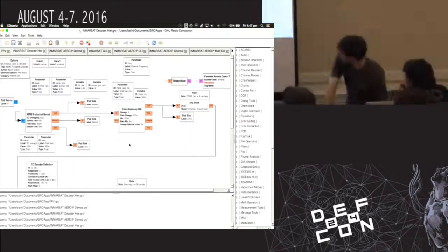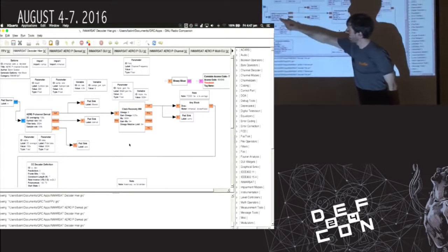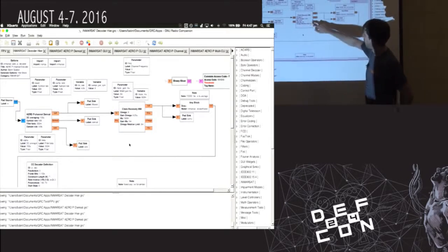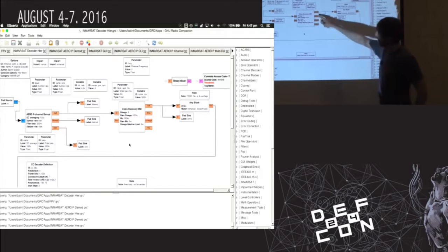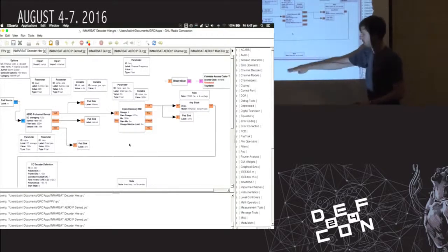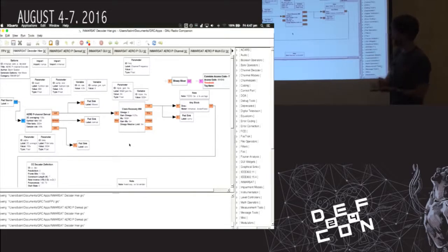And then we go and actually look at how that's used here. So this is the next hierarchical block layer. So you've got the demod here, and then you go into clock recovery. So here I've oversampled by 8 because it's quite cheap here at this low rate. And then once you get your soft bits out, so remember these are not hard 1s and 0s. These are soft bits because remember in that bottom diagram here when they were just above and below 0, they were sort of sprinkled around there with that separation, but they're not sort of your hard 1 and 0 bit. That will go into this block.